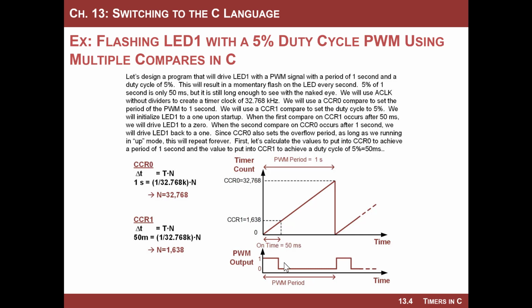You're going to have an electrical signal, and it is going to have a duty cycle and a period. The period of a digital signal is always like edge to like edge. So it's basically rising edge to rising edge or falling edge to falling edge. But you're also going to generate a signal that's going to have a duty cycle.